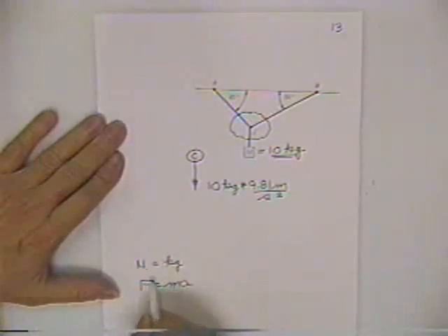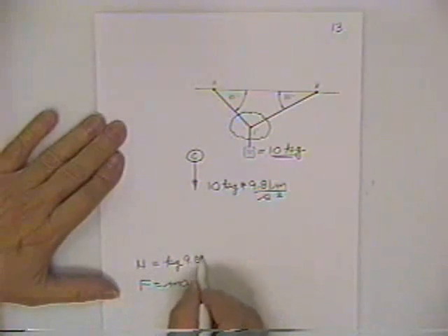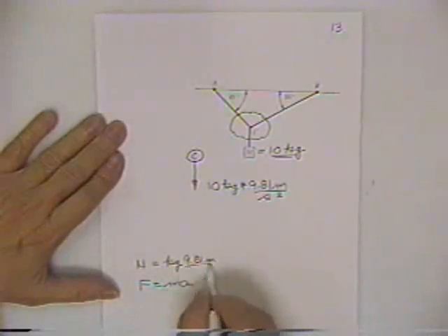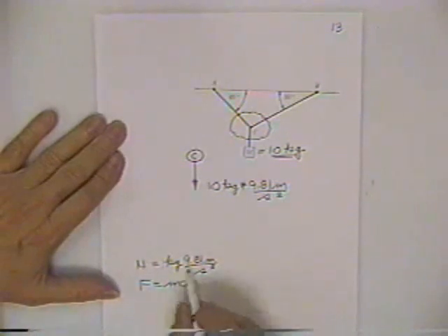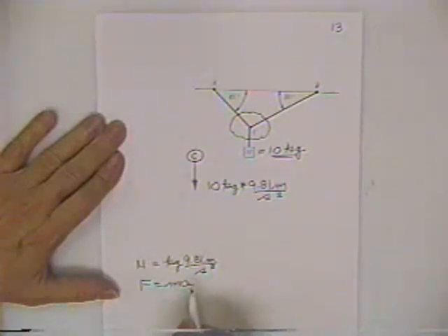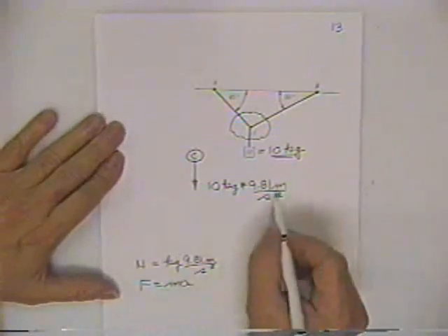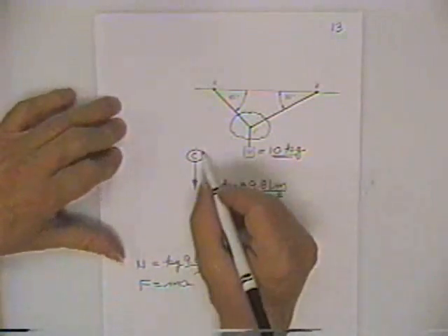What do you have to multiply it by to make it a force? You multiply it times g, and that's 9.81 meters per second per second. And a kilogram meter per second squared is the same thing. They gave that assemblage of units the name newtons, and so that's why we have to multiply times 9.81 to turn it into a force.